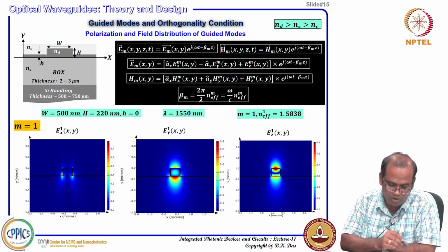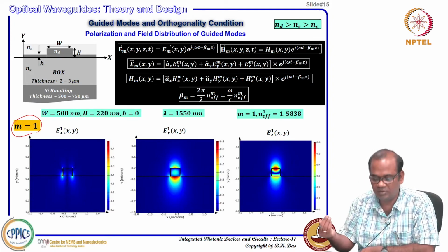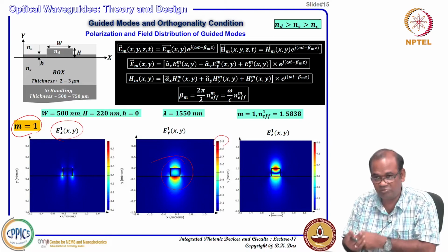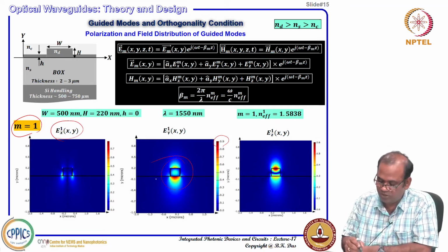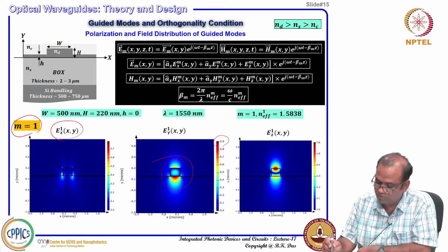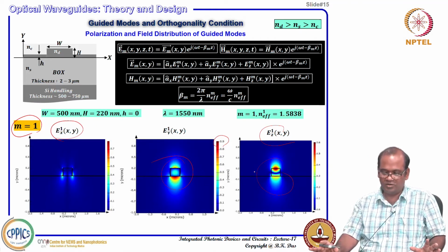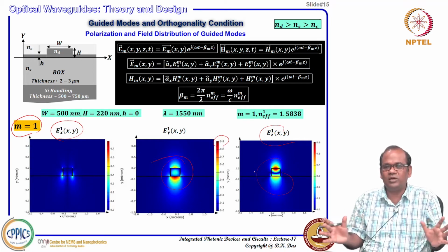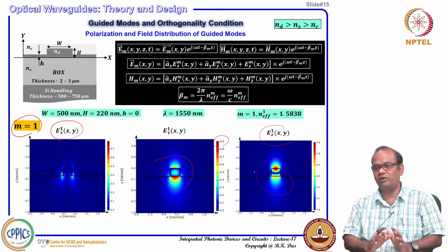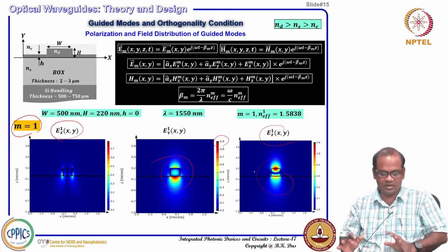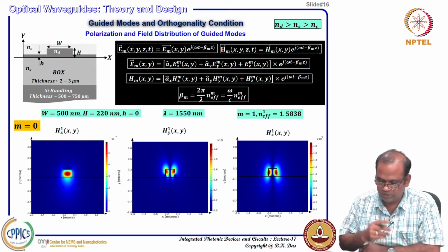Now, go to the m equal to 1 solution. Next eigenvalue, eigenvector, you see Ex1 is almost nothing, it is 0.7 on the given scale, and Ey1 will be stronger, it is up to 0.9. You are seeing that the field distribution is different now. It is a higher order mode, the field distribution is different, and then you see the Z component is like this. So all the 6 components are present, some of them stronger, some of them not so strong. So we know how the different field distributions look, and for this particular silicon waveguide we are confirmed that whatever we predicted in full vectorial solutions, that all the 6 components will be there, they are coming.